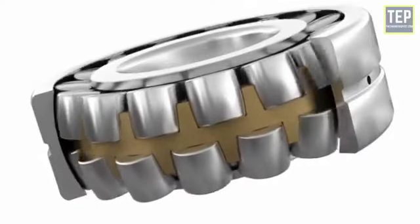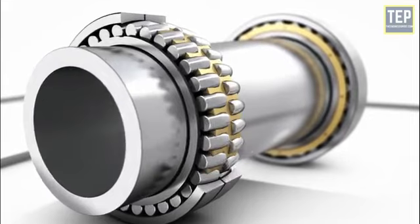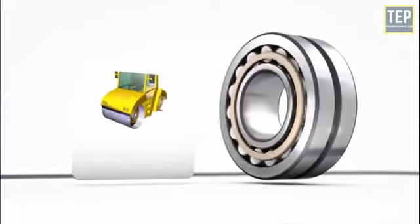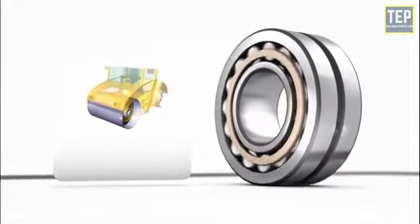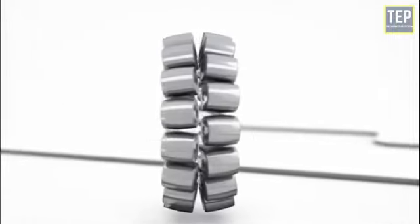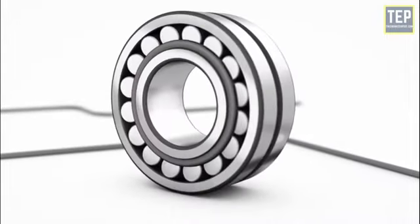Roller bearings maintain accurate alignment of every part over a long period of time and can carry heavy momentary load. This renders them suitable for machinery which requires frequent starts and stops. Rollers make line contact with their races, while balls make point contact. It has a higher load carrying capacity.